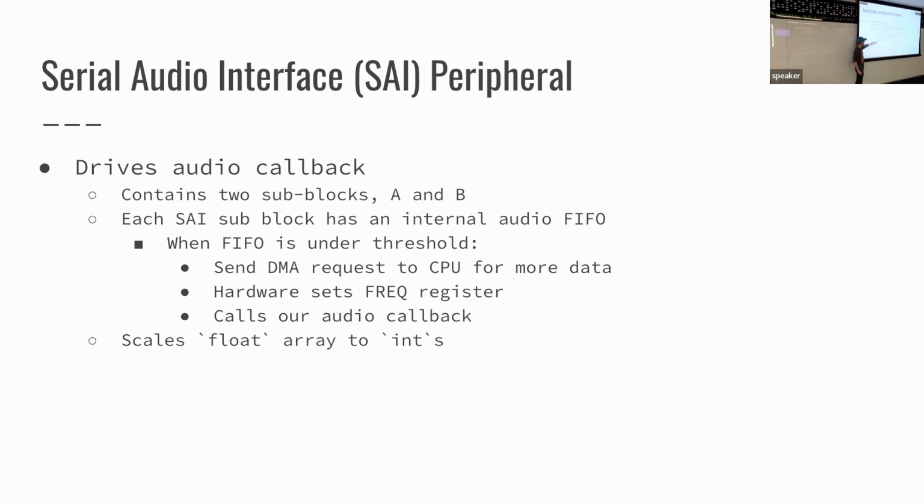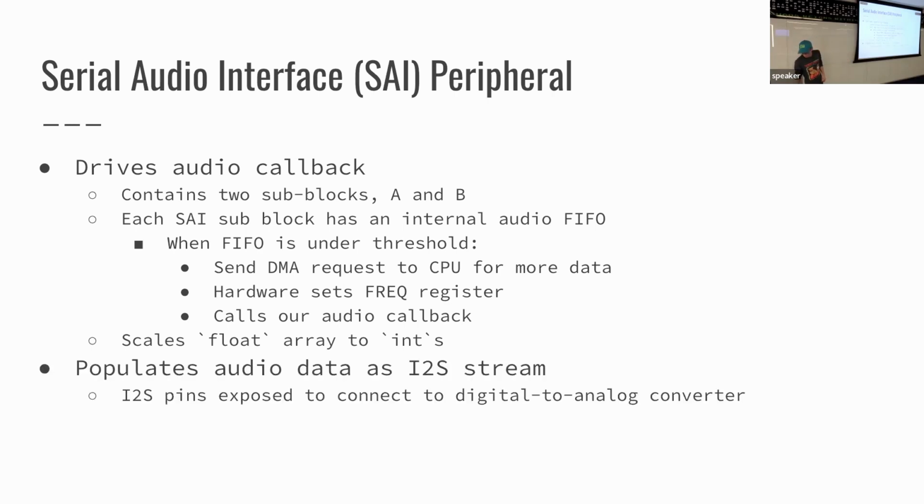We've delivered floats, so the bit depth comes in here. We scale those normalized floats to a particular integer value based on how much width we have to work with. And then in the Daisy case, these I2S streams come out in two locations. There is the internal one, which is kind of the whole reason to use the Daisy.